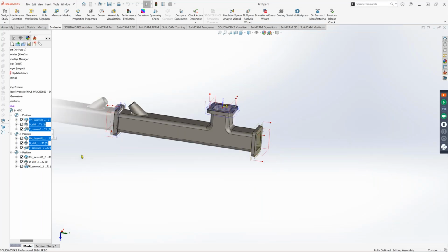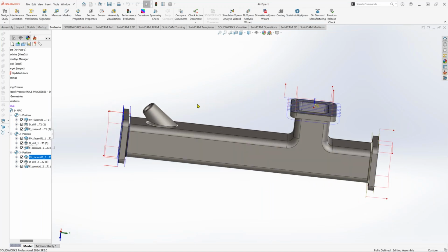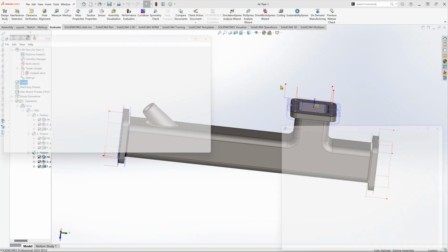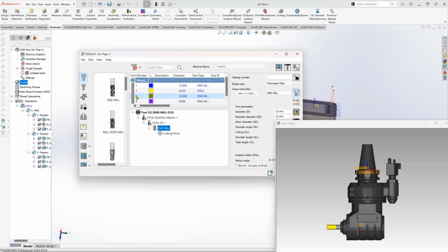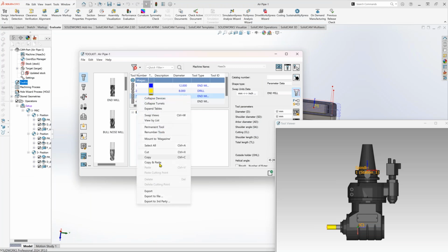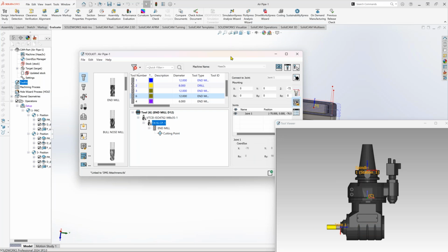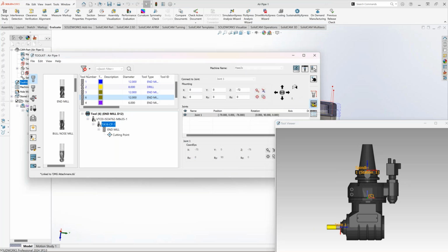The biggest question is, let's finish the third one just to be sure we have everything done. Go back again to the ToolKit and copy the tools I made. For example, now I make a copy of this tool. I go to the orientation component, to the connection point, and orient it here 180 degrees around Z.